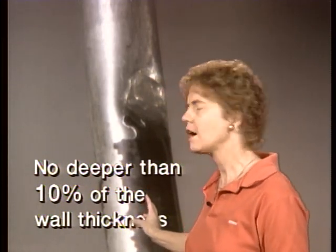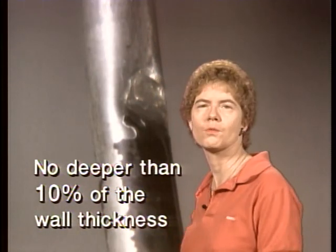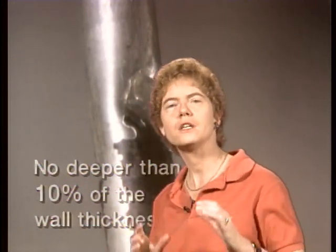So if you've got a scratch or nick in the straight section, it can be no deeper than 10% of the wall thickness, or if it's in the heel of a bend, which means the outside part of a bend, you can't have any scratches or nicks there.